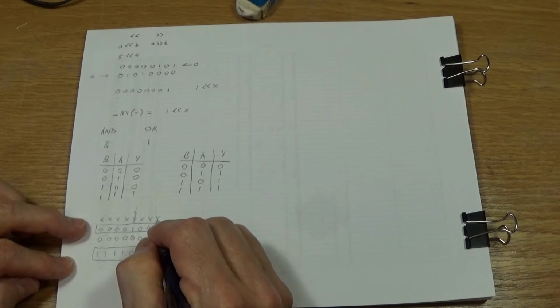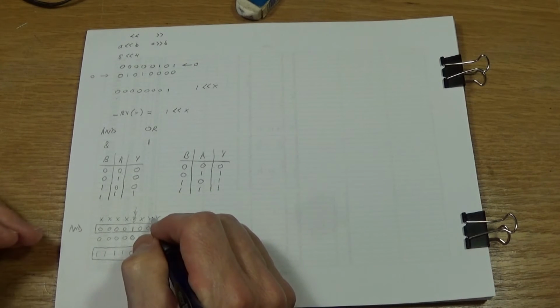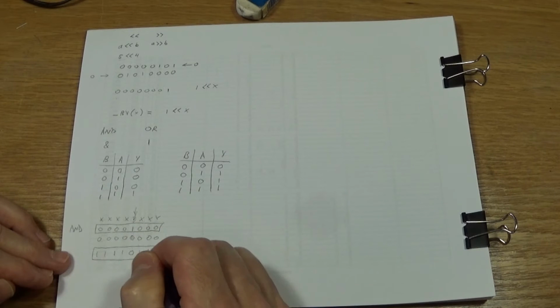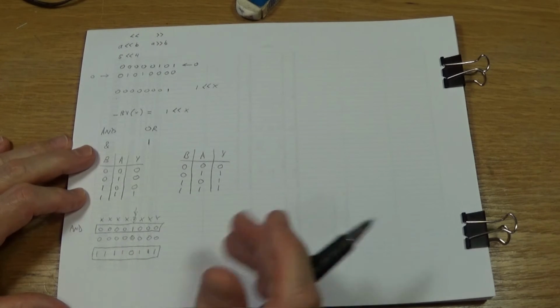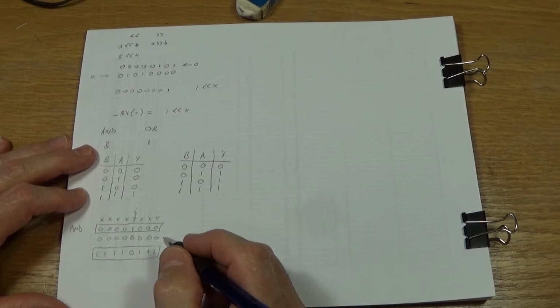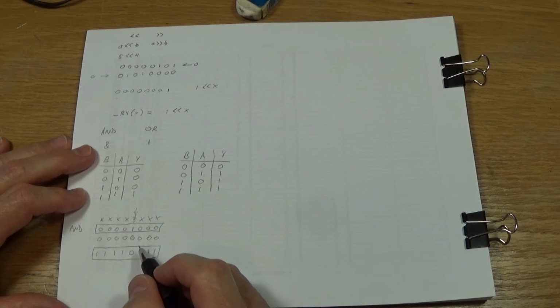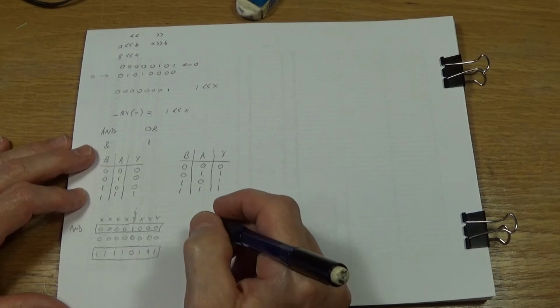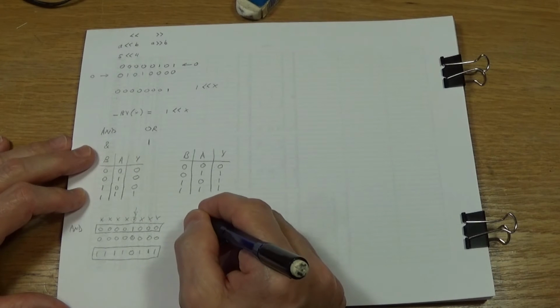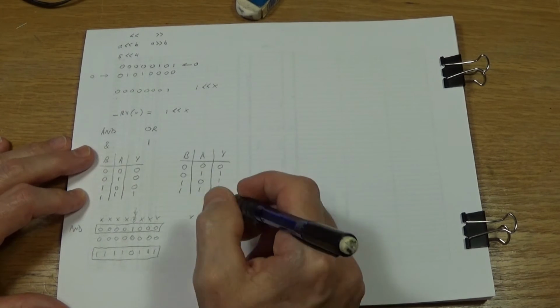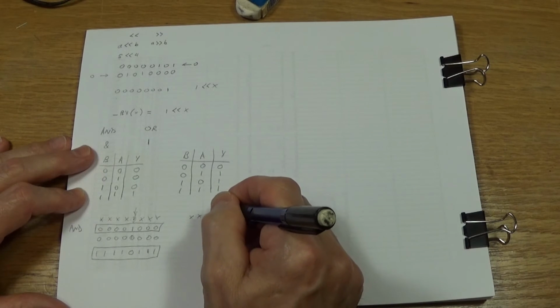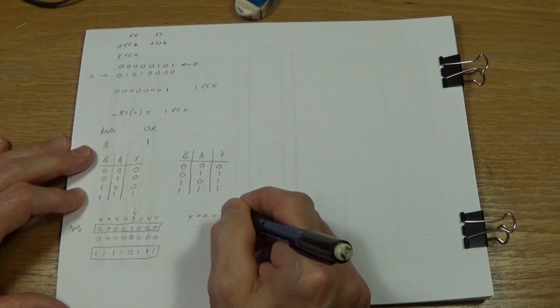But all the rest of these bits are unchanged, so we can read that register, AND it with this mask, and then put it back into that register. And that way we've cleared that 1 bit. Now there's another thing we could do if we want to set a bit in a register. We use the OR function. So again, let's use the same example. We've got this register. We don't care what those bits are. But this is the one that we want to make into a 1.